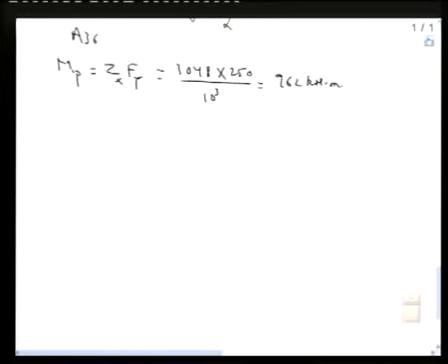This value Zx, you will find it multiplied by 10 to the 6, and this is multiplied by 10 to the 6, and to find kilonewton meter, you have to make some changes from Newton millimeter to kilonewton meter. I think this is multiplied by 10 to the power 3, and this should be multiplied by 10 to the power 6. So if you take this by this, you get 762.